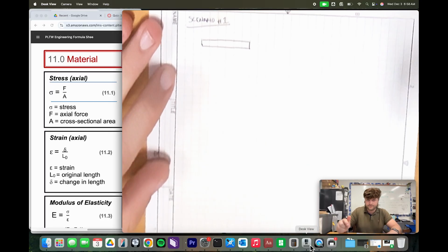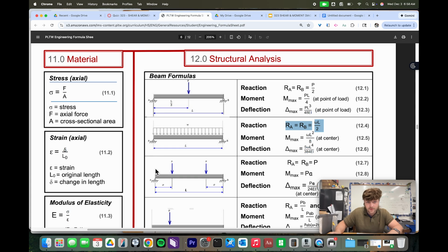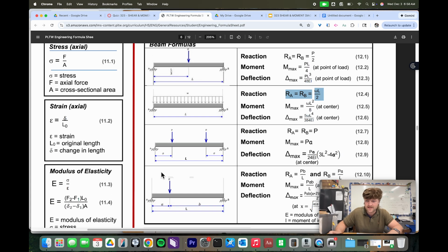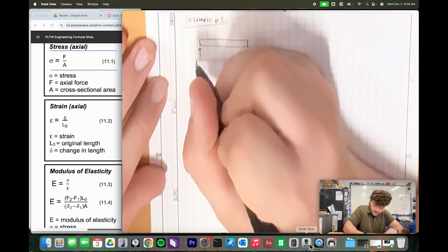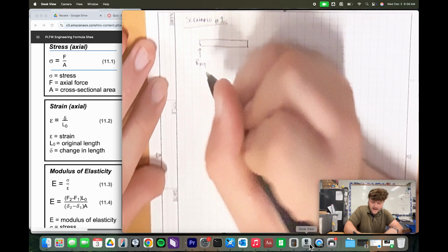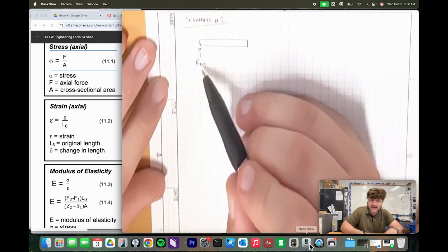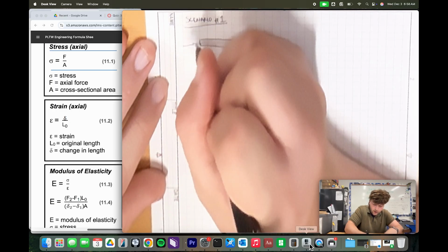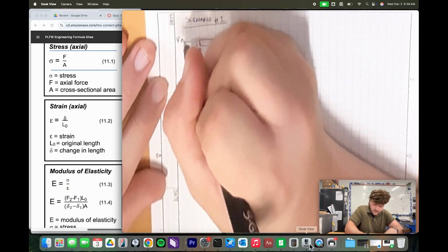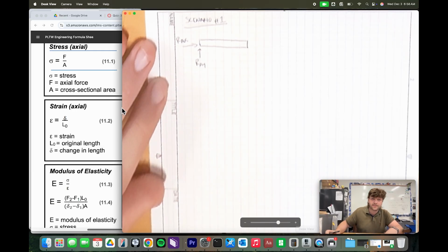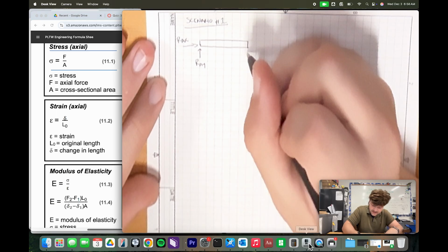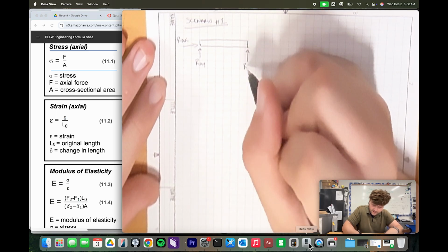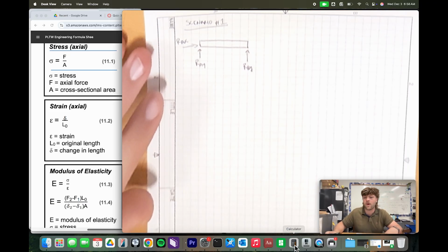And then it is the case where we have pin supports for all of these, right? So as you'll remember, a pin support has an X component force as well as a Y component force for the reaction. So I'm just going to go ahead and put in here R, A, Y. And so that's for reaction force at A, and it's the Y component. We're also going to have the reaction force at A, and there's going to be the X component. And then now whenever we look at this roller, for rollers, there's just the Y component of the reaction force for those. They only supply a Y component.